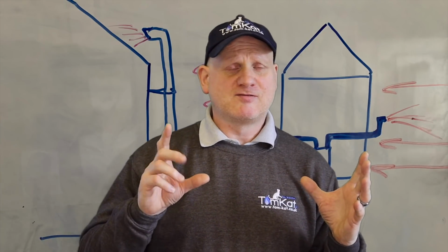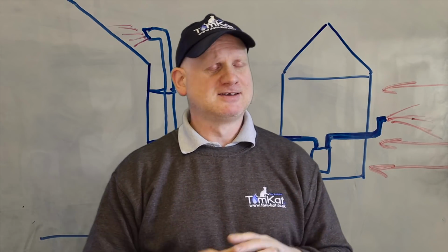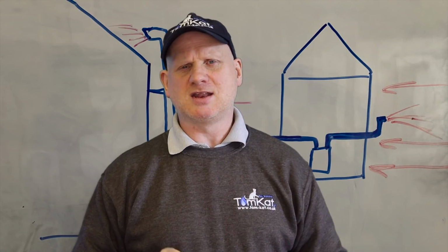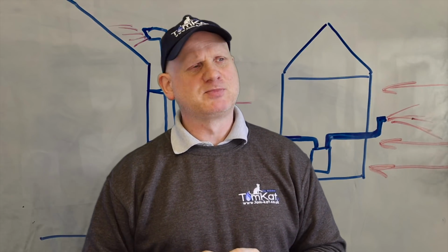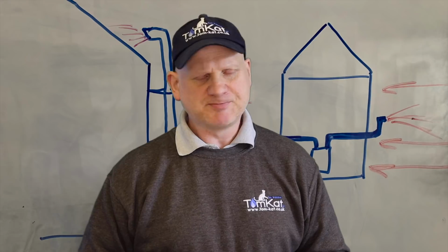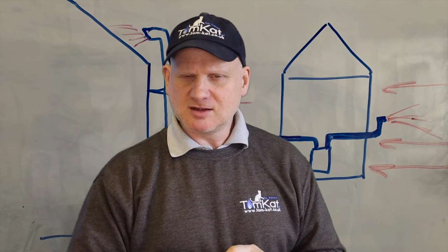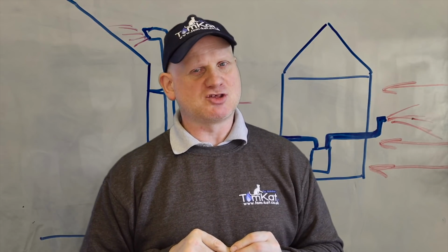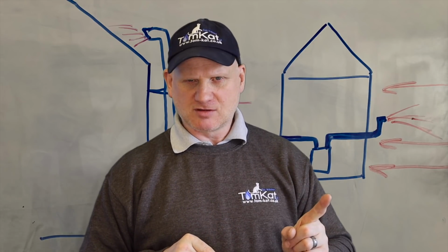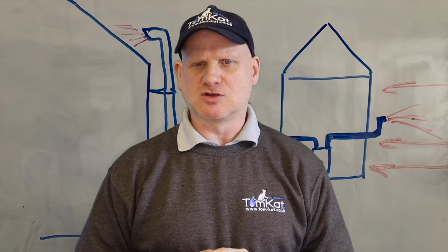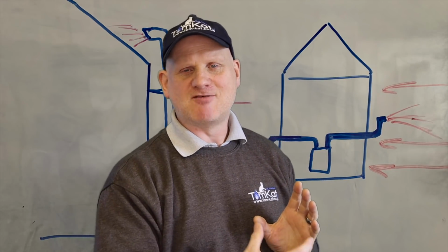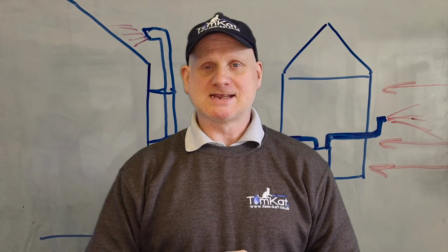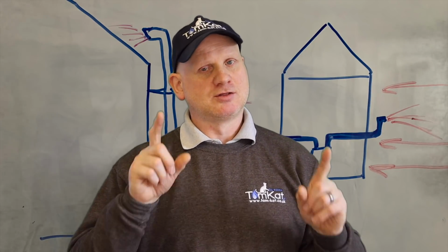And finally, using a Plume Management Kit, like I said right at the very beginning, to get you out of an illegal installation. So if you get a conservatory and the flue flues into the conservatory, you cannot use a Plume Management Kit to take the products of combustion out through the conservatory roof and leave the air inlet in the conservatory. That's a complete no-no. So don't do it.